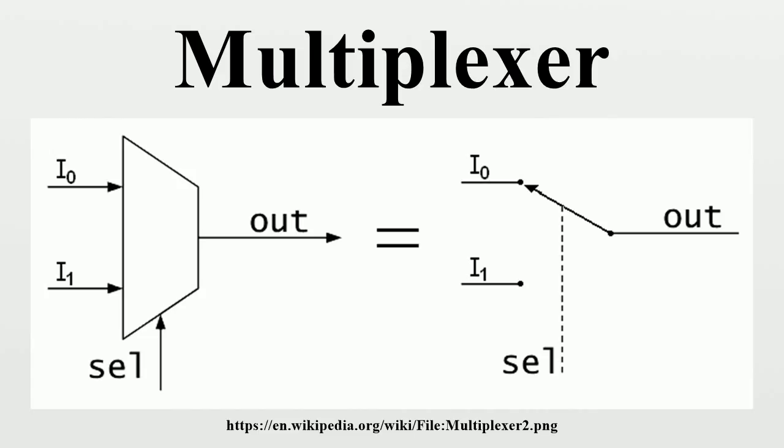This means that any function of the selection bits can be constructed by logically ORing the correct set of outputs. If X is the input and S is the selector, and A and B are the outputs. List of ICs which provide demultiplexing. The 7400 series has several ICs that contain demultiplexers.